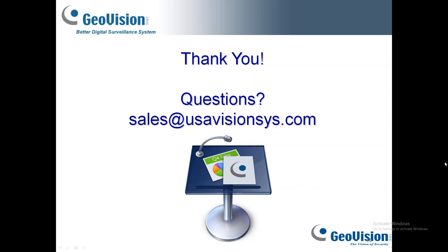The next one here is about the EMAP. It just is asking, is the EMAP available in the 17.3 software? Yes, it is. It's actually available in a couple versions before 17.3. So yes, that is in there. If you go into the VMS folder, you'll see an EMAP editor program, and that's where you can go in and create and build your EMAP. If you want some more guidance on that, again, just please reach out to us on this email.